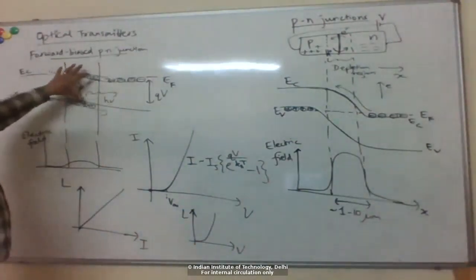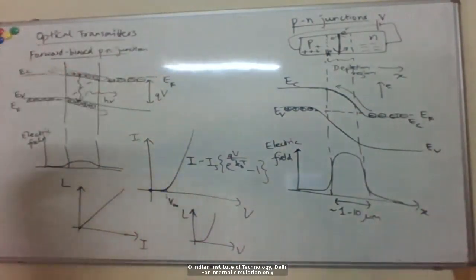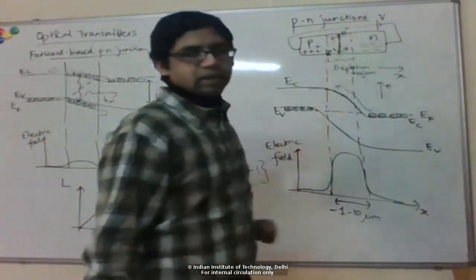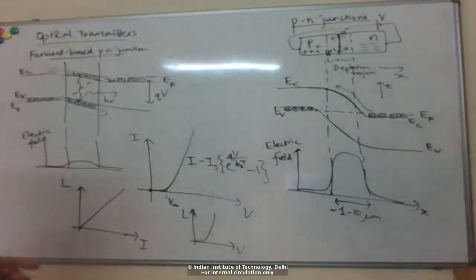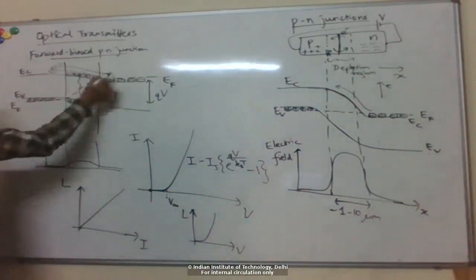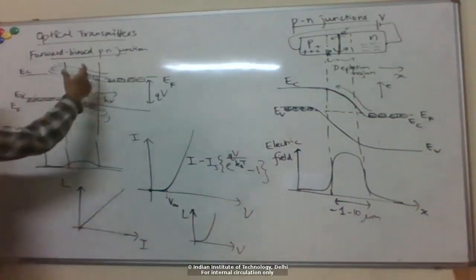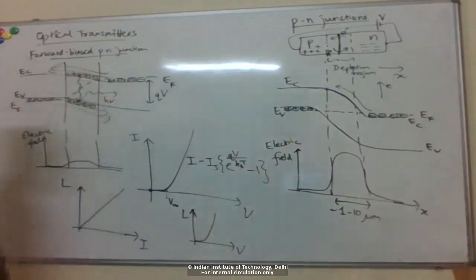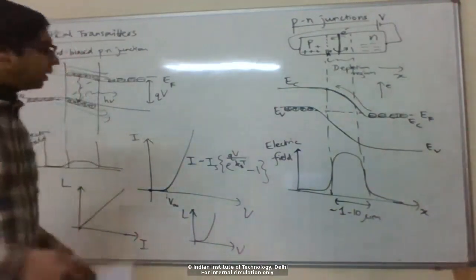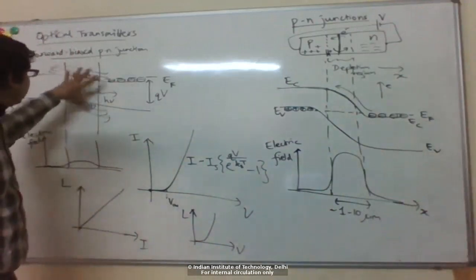If you take this most basic PN junction, which is made of the same material, we had the same material here, and we just doped it P-type on one side and N-type on the other, and this interface was created. This is known as a homojunction. Homo stands for one, so there is only one type of material with P and N. You can see that this type of device probably is not very efficient, because these electrons are traveling fast across this region, and similarly holes are traveling fast across this region. So the fraction of carriers which will recombine here to emit light will probably be very small. There is some rate at which this radiative recombination happens, so there is some radiative lifetime, which roughly tells you how long the electron or the hole needs to spend here before they recombine.